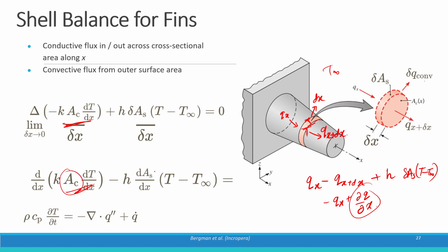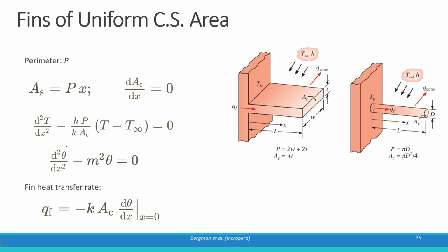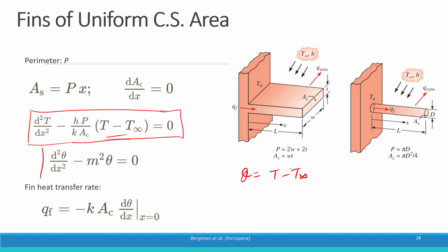area, that for conduction it is a cross section area, similarly for convection it will be the surface area. If you put the value of area and then integrate it over the entire length, that is x equal to 0 to L, you can get these equations, the general equations for this fin. So whereby you can just define this theta as T minus T infinity, that is a temperature difference between the surface and the ambient air temperature.